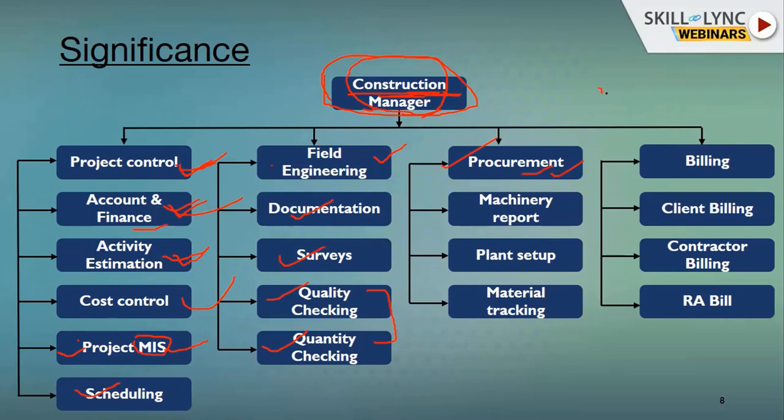If suppose somewhere required it is 10 cubic meter and we have used 8 cubic meter quantity, then we saved the quantity. No, we should not have that kind of a philosophy. That means we have optimized our quality. Okay, we are somehow lagging to maintain the quality. That is why we have not used 10 cubic meter. So that is not that we have saved 2 cubic meter concrete, but we have compromised with our quality. So that part we will see in procurement.